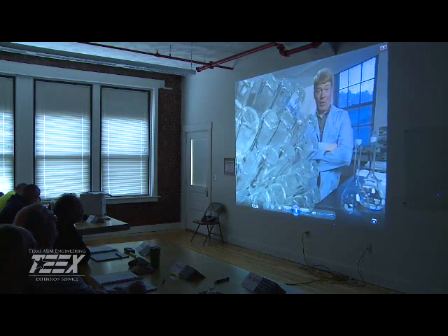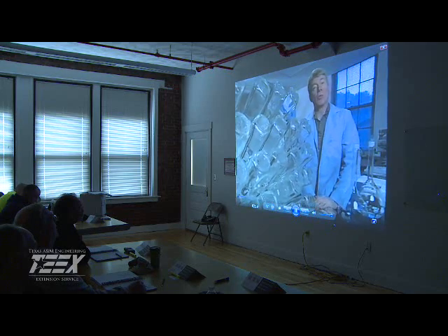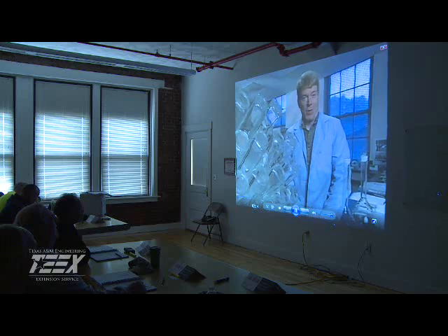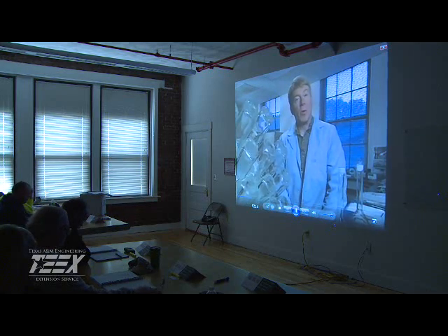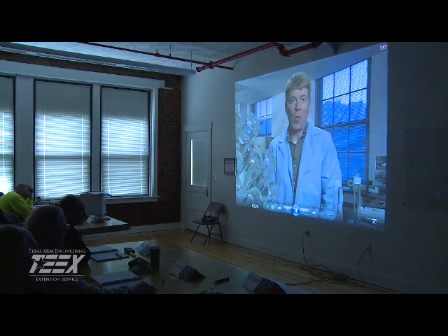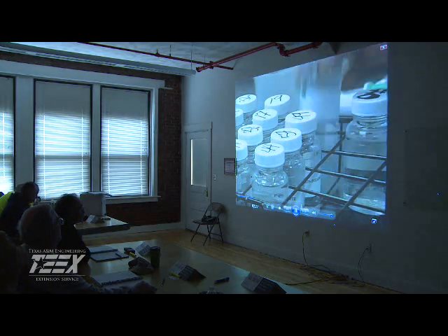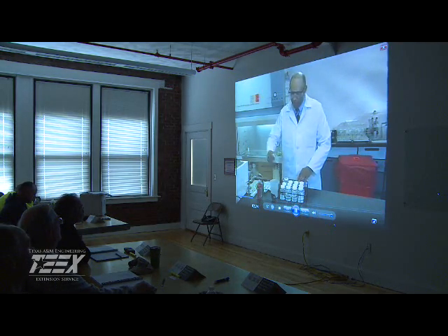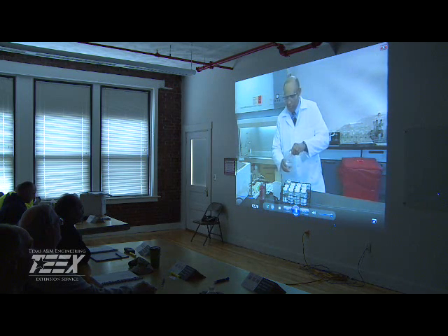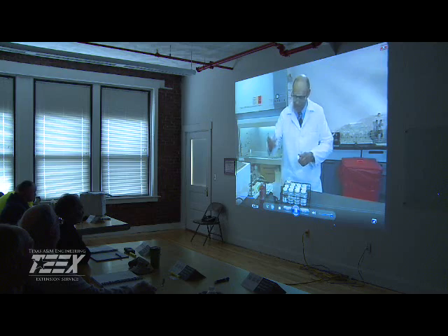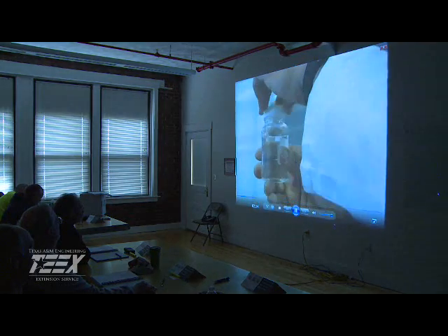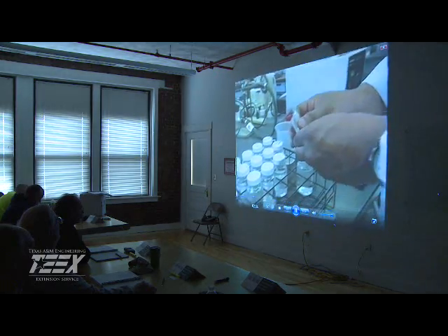The coliform group of bacteria, also called total coliforms, is an ideal indicator in drinking water. Coliform bacteria is easily detected. When it's found in water, it's assumed pathogens are present too. The presence of coliform bacteria is strong evidence the water may be unsafe to drink. That's why accurate sampling is imperative. It tells us if total coliforms are present. These samples are an integral part of the effort to protect public health.